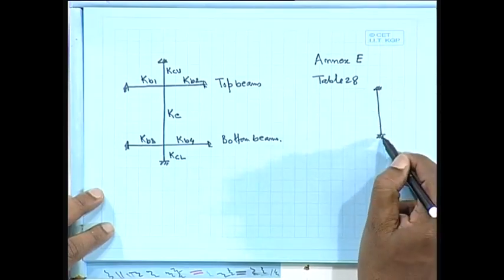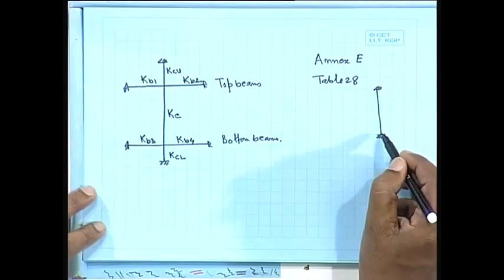That is a case where it is clearly mentioned, but when you are talking about a building frame which you have to design, you have to find out the effective length, and it will not fall out of those 7 cases. So, how shall we find that? We have to find it according to the stiffness. So, you have to find out the stiffness, and accordingly calculate the effective length.